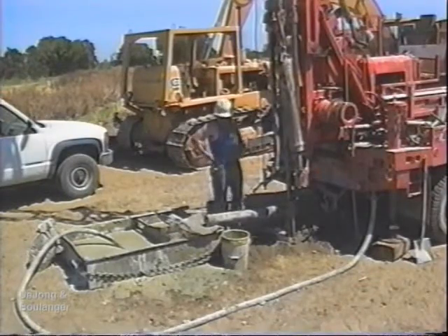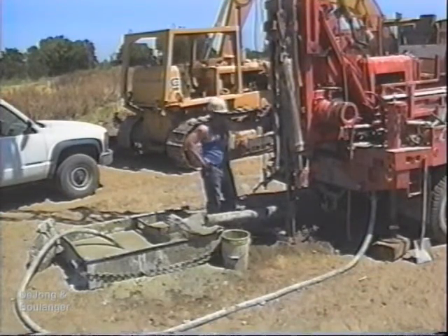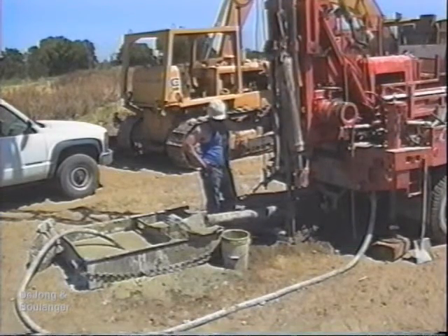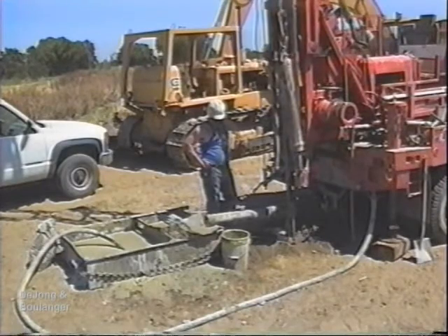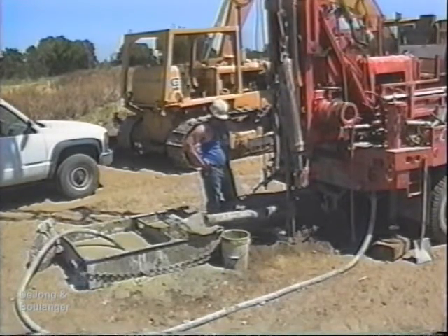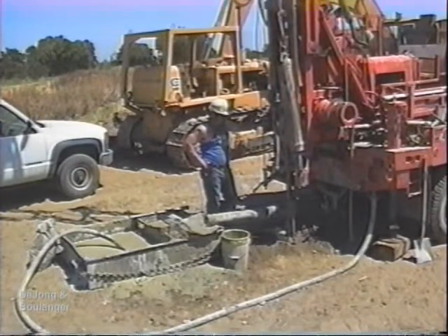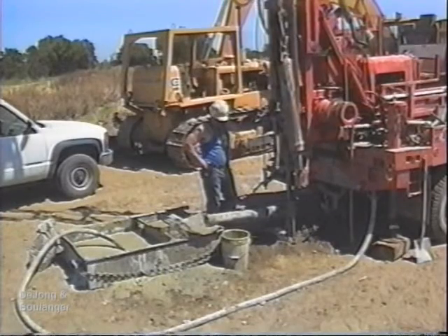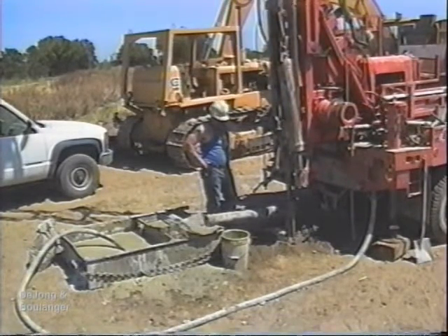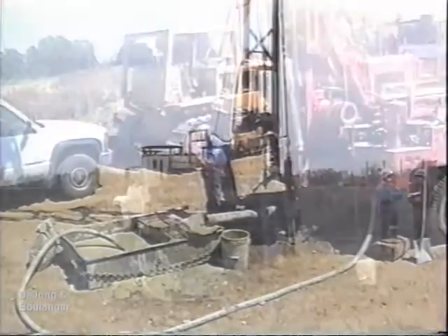Generally, the mud rotary method is faster than other methods and usually results in less disturbance to the soil being sampled. This method, however, can have difficulties in gravel and cobble layers because the drilling fluid may drain freely into these layers, or the drilling process may not break up the larger particles or remove them from the hole. In the latter case, the drill bit and stem may bind in the hole. Despite these difficulties, mud rotary drilling generally works better in gravelly deposits than either solid stem or hollow stem augers.